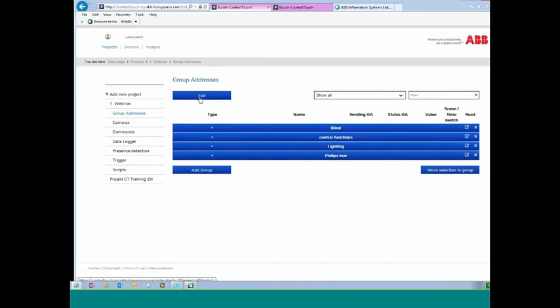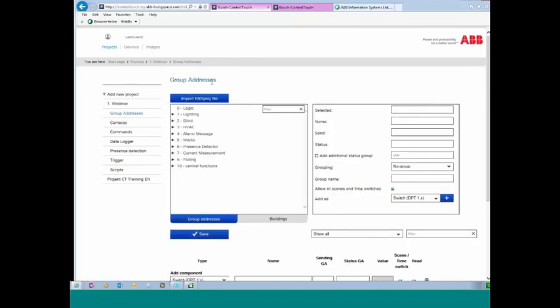So now the target is I want to display temperature. I want also to change operation mode, and I also want to change a new set point. As Torsten mentioned, the control touch is only a slave. That means somewhere in your project, you need to have a real RTC controller. The slave, like here, the control touch, is an extension unit. That means you are just sending some requests to your master for changing operation mode or changing the set point.